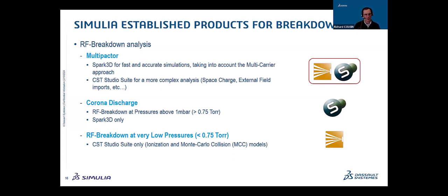But for complex structures where you would like to take into account more physics, you can use CST Studio Suite, where the space charge can be taken into account. You can even import any external fields, and then compute the multipactor analysis using the PIC solver or the ES-PIC solver.